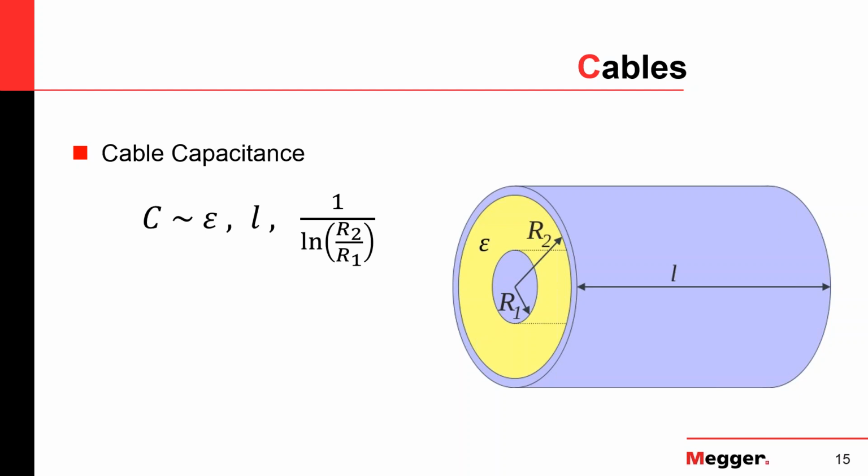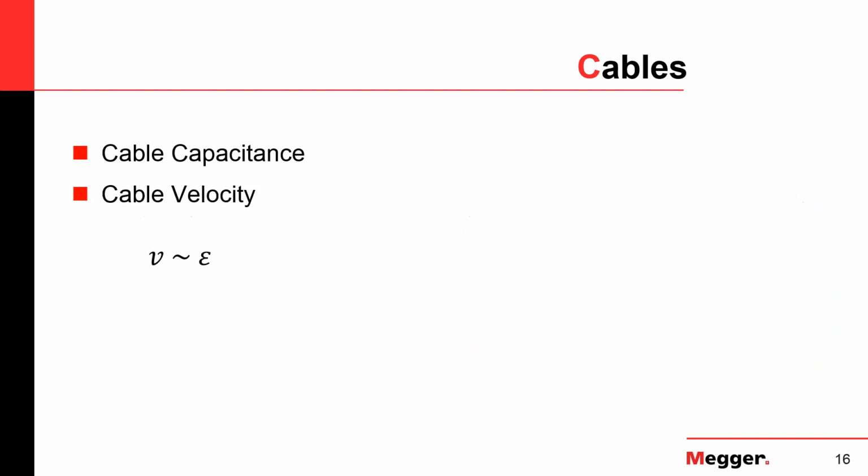And you can see it's not a nice number. There's some crazy math there, and that only pretty much determines that if you would plot the field strength and the voltage distribution starting from the center conductor to the neutral, this is not linear. It's not a nice straight line in the diagram. The closer you get to the center conductor, the more stress the insulation is actually experiencing.